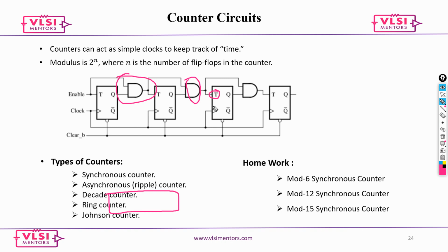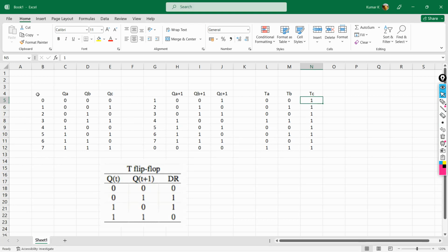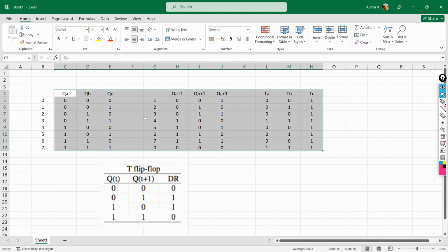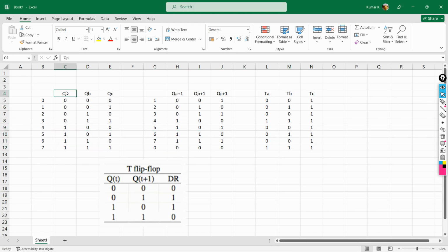So this is how we actually design the whole sequential circuits. Now don't look at this only for counter, this can be applied more generally. The first step is to come up with this kind of table where you will have your current state, next state, and the corresponding input that needs to be applied so that you get your system working. All right. So any question here? How do we design a counter and all that?